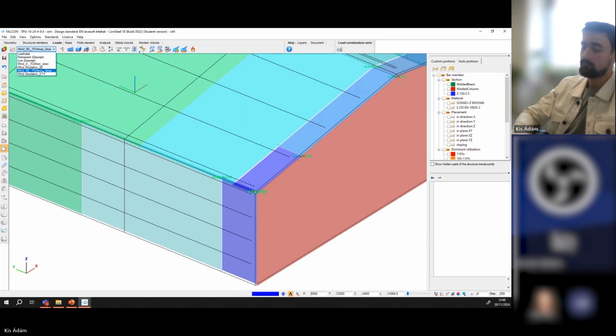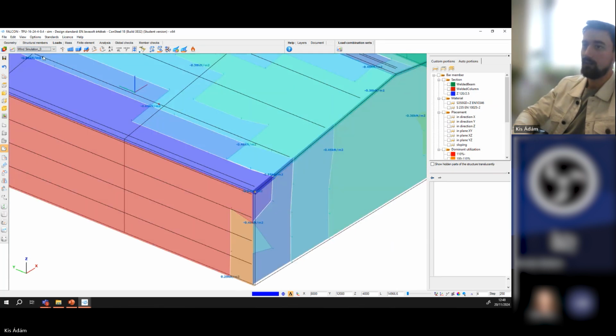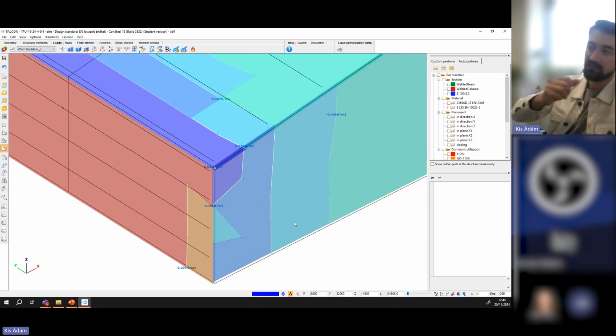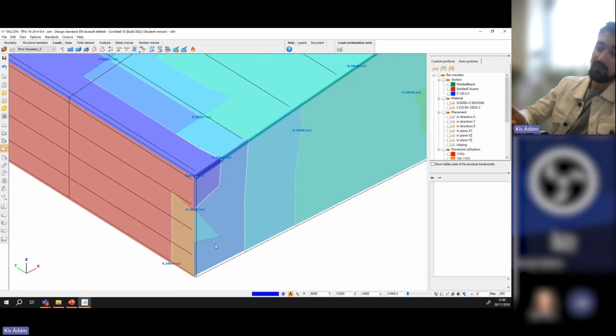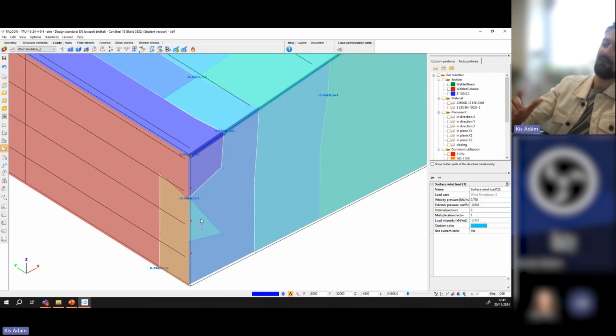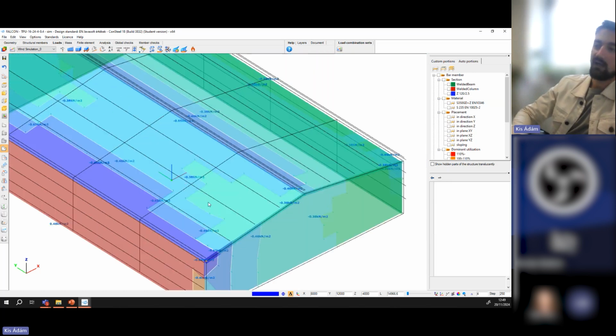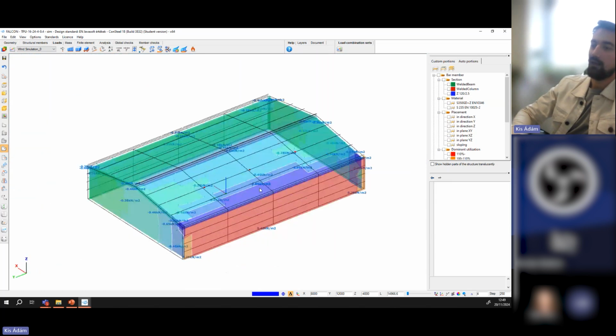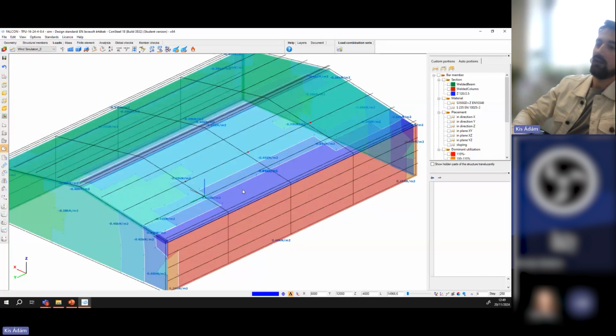And this was because I accepted the recommended value according to the building dimensions, but I also have to take care of the proportions of the building, because in this scenario, for example, I only have 3 meshes here close to the wall, which leads to this triangular mesh disturbance, and it is not that fluent, for example, this mesh. But again, these are situations which you can iteratively resolve, and you have to see the bigger picture.